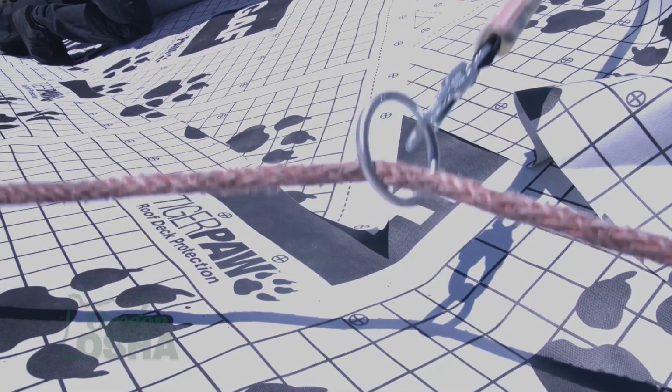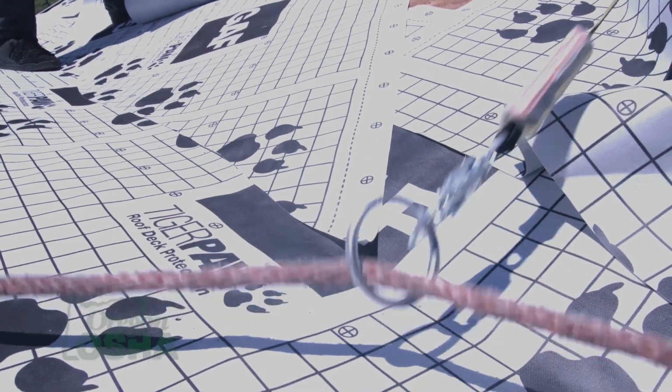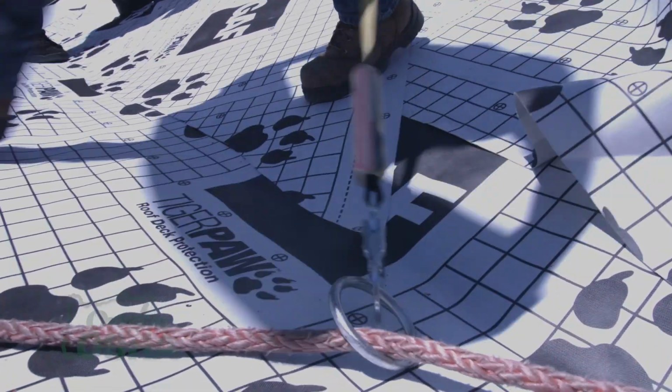There are systems that can go up on the ridge of a roof that hold more than one worker. You can have systems that can hold up to 4 workers off of one certified anchor point or engineered style anchor point. There are also horizontal lifelines that can be temporarily installed on a roof that allow workers to move back and forth across the roof, connect more than one worker, up to 2 workers, and use the ropes and rope grabs up and down as they're going from the eaves up to the peak, doing that roofing. Provides a lot of mobility. They can set up a fall restraint system very easily that way.